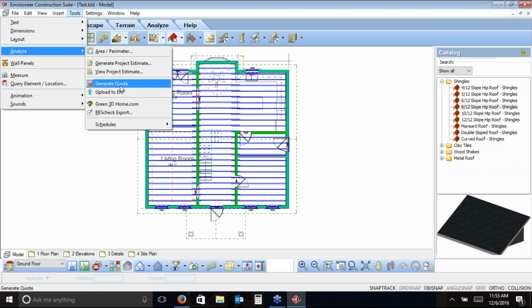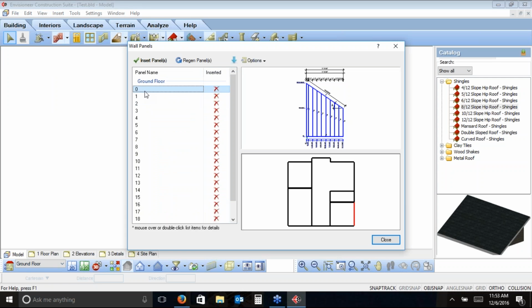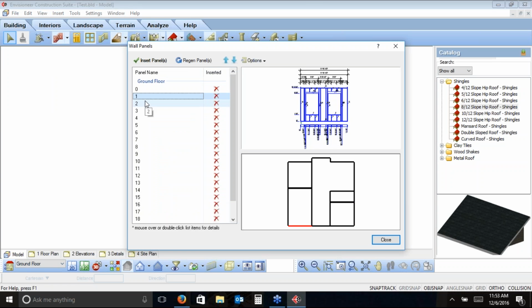We also briefly discussed value-added information. We have this 3D model. If you want to also add wall panel diagrams, you can also produce those. They're automatic. It knows each individual wall that it has, and it can create the wall panel diagrams associated with those. So not only are you supplying the materials, but also the diagram of how that's all going to be put together. So that could be a great way to add extra value to your builders.